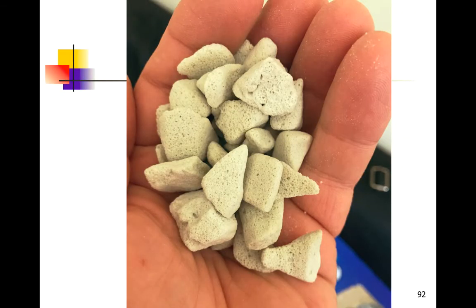The grow stone, the media, again, it's recycled glass that's heated, air is injected into it, and once it cools, it creates a pumice stone. It has about an 87% void volume. The aggregate itself actually has pores that go all the way through, so we will get not only treatment on the surface of the media, but also in the internal portions of the media as well. Much better than just a standard rock type media.